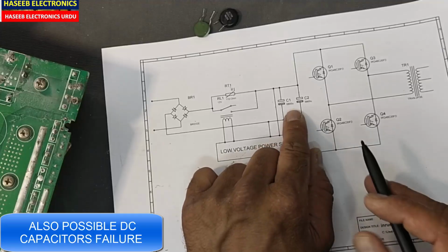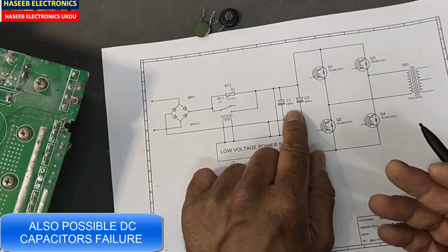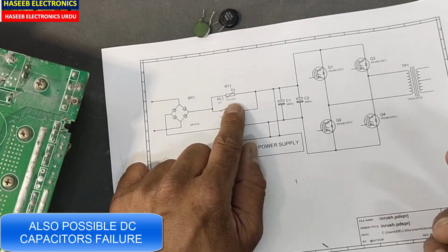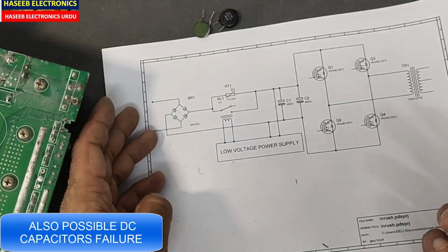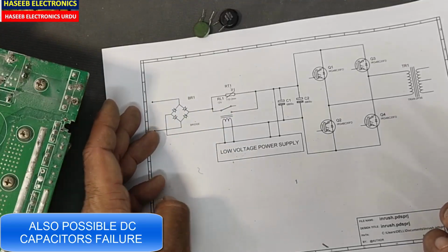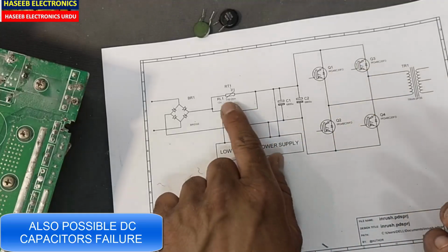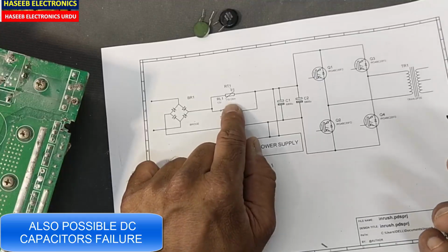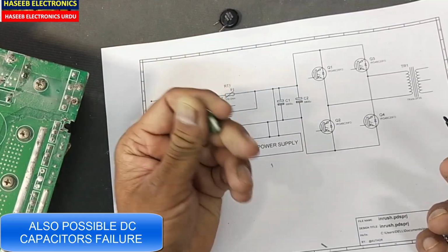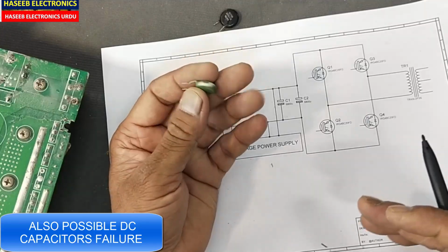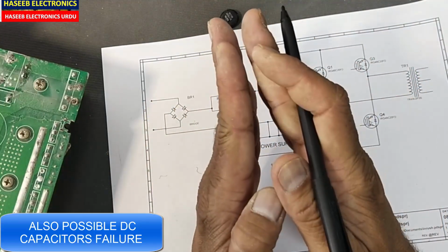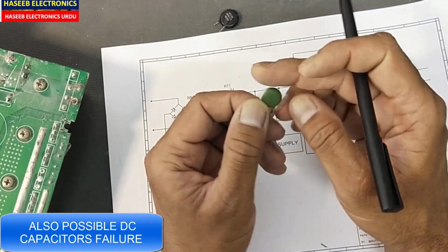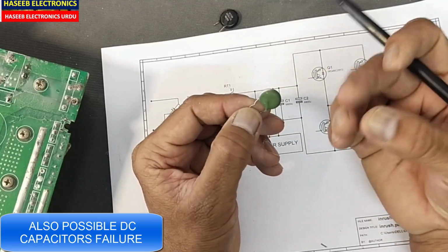At that time, the capacitors are not being charged, and this capacitor and this NTC are a total 100 ohm resistor. If it is a 100 ohm resistor and we are applying 220 volt here, at that time it will draw more and more current. What will happen? At a specific level, its internal plates will be damaged,